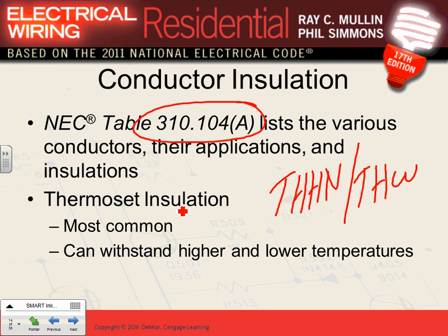Now we're coming to commercial. We'll talk about this when we go to commercial too. We're still residential. The stuff that we use in residential is NM cable. Almost all the stuff that we'll be using is NM cable. And NM cable is made out of THHN conductors inside it. NMB, absolutely. NM cable, NMB. Most common, we'll talk about NMB and the other application in C and S.